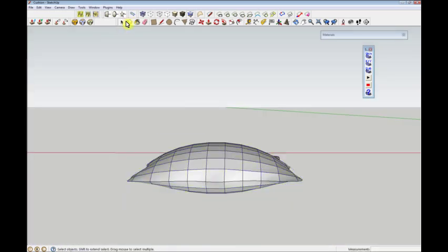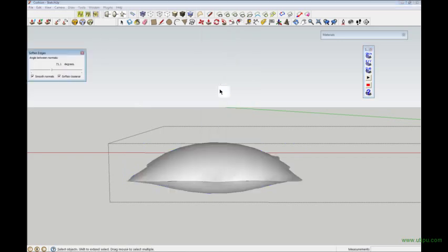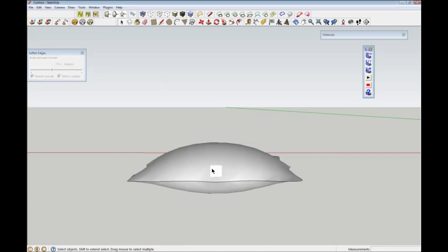So then now, if I select that, sorry, I'm going to do something else first. I'm going to soften it. So I'm going to go into the editing mode of it, select all, right click, soften. There you go. I would have clicked soften coplanar, and that's fine then. Soften the edges. Move it to about 70ish, something like that. That's fine. Okay, great.